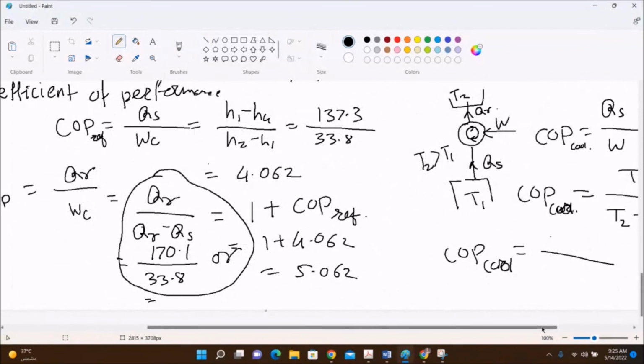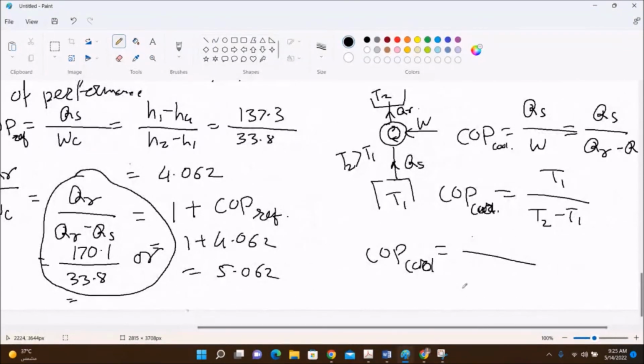It is very important that all these temperatures be in Kelvin. In the lab manual the formula is written with 273. Why 273? Because if temperature T1 is in degree centigrade, then here you put Kelvin. Since the table gives temperature in Kelvin, your answer will be wrong by this formula, so don't use this.